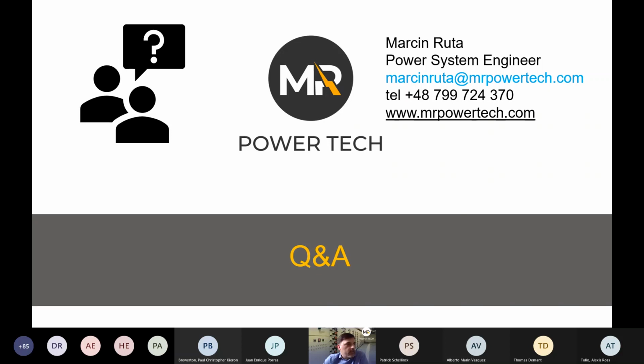As I have understood, in the US the arc flash prevention and mitigation falls into two different fields of legislation. One is OSHA or NFPA rules for work safety. The other part is the arc flash study itself, and that falls to IEEE 1584. Is this a correct interpretation? Yeah, I would say yes, but IEEE 1584 is a guide to make calculations, so it's just one of the methods. In NFPA you actually have a few methods that you can use. IEEE is just the most popular one because it's the best documented, with the best test and empirical data. So yes, that's correct.